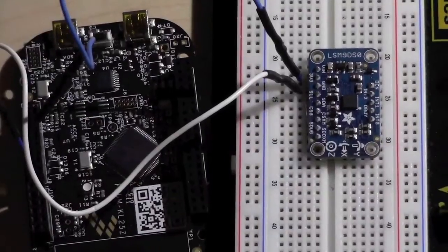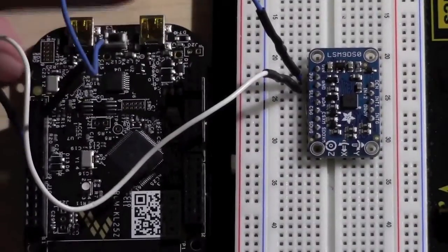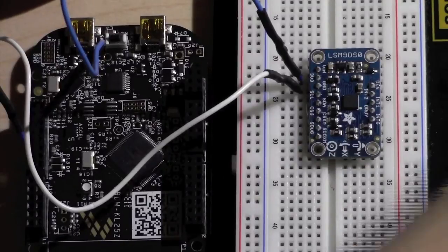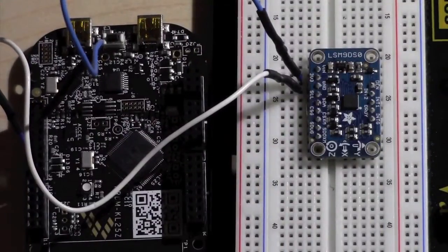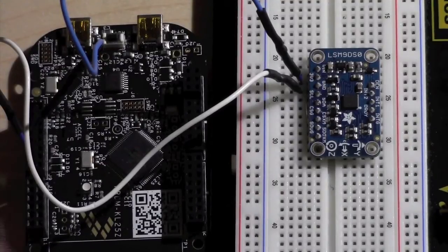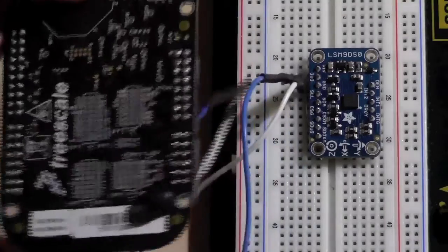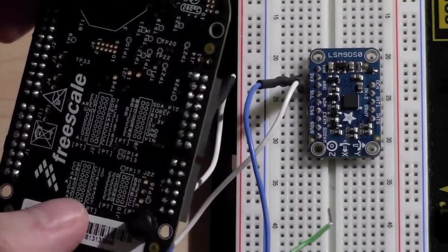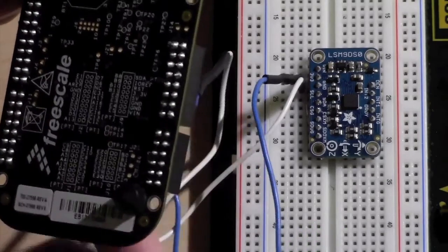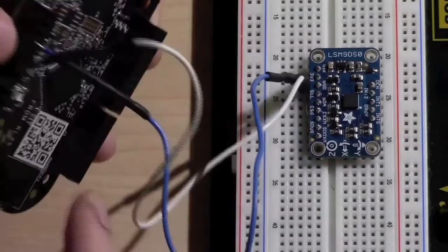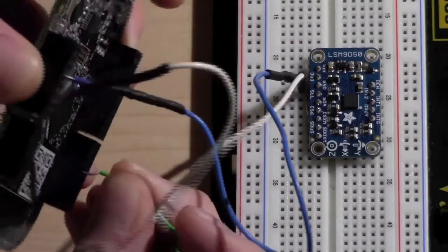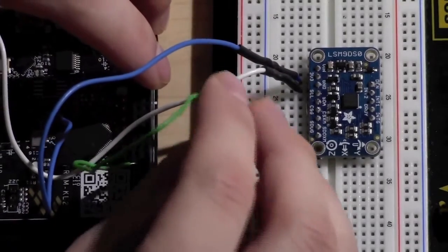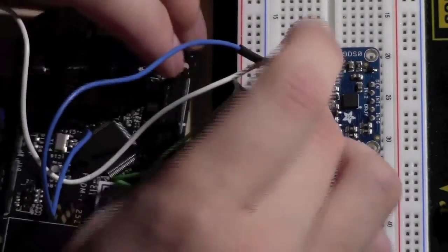Okay, once we have that all set up, now we need to go ahead and select the SPI pins that we want to use. We're going to be using PTC6, PTC7, and PTC5. PTC5 is for the clock, so let's go ahead and locate PTC5 here. PTC5 in this case is right over here. So it's the middle pin. So it's pins 1, 2, 3, 4 down from there. So 1, 2, 3, 4 right here. It's going to be connecting to our clock, so it's going to be connected to SCL on this chip.